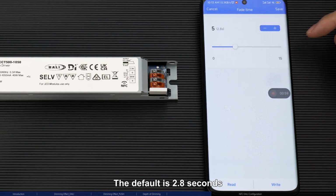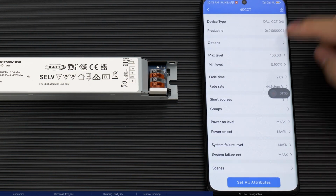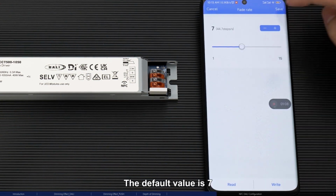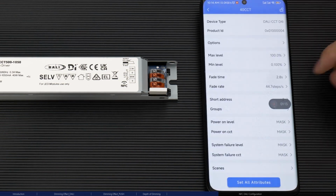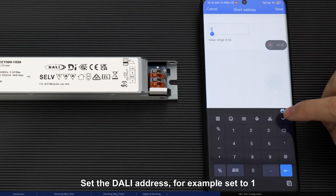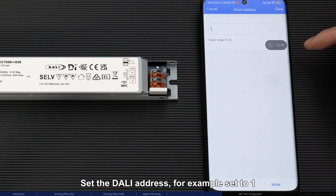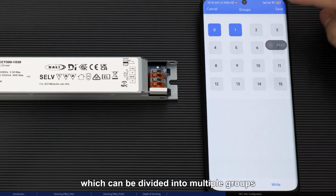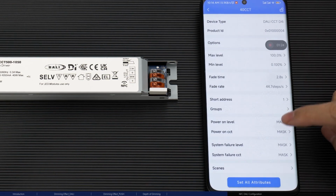The default is 2.8 seconds. Fade rate, dimming rate for long press buttons. The default value is 7. Short address, set the DALI address, for example set to 1. Groups, set up grouping, which can be divided into multiple groups.